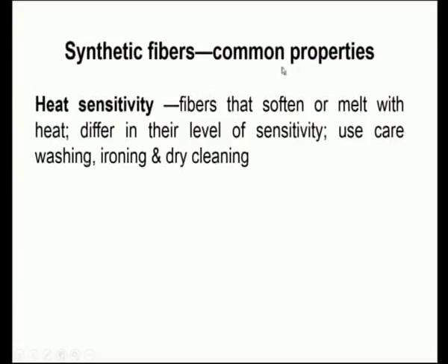Synthetic fibers' common properties. One property is heat sensitivity. Fibers soften or melt with heat and differ in their level of sensitivity, so use care in washing, ironing and dry cleaning. Heat is one of the parameters: if you heat any fiber material, synthetic or natural, it will become elastic, or soft, or it will melt.